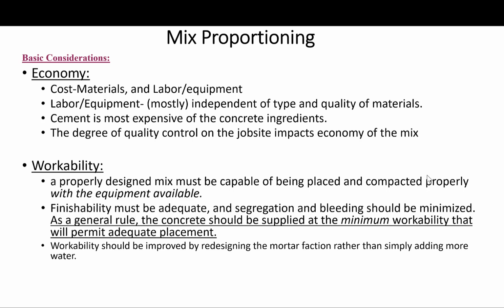Also, the economy of a particular mix design should be related to the degree of quality control that can be expected on a job. The design concrete strength must be higher than the specified minimum compressive strength because of the inherent variability of the concrete. So again, you have to account for less than perfect practices in the field. I mean, if you can guarantee 100% the quality control practices, okay, but it can never be guaranteed. That's why the design strength will be higher than the specified minimum strength.